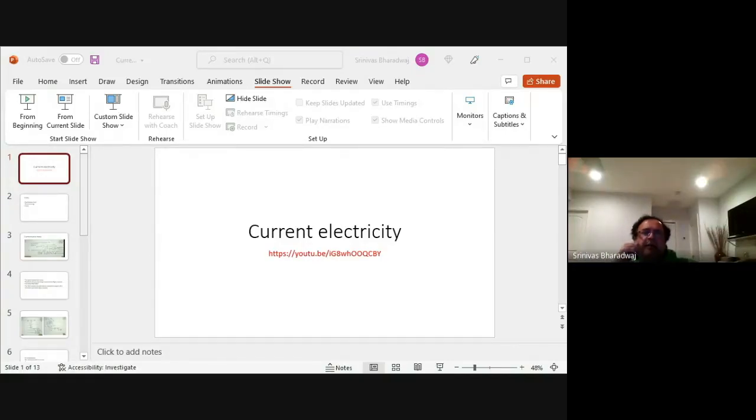Now, an ideal battery will have no internal resistance, but most normal batteries will have an internal resistance, which will get added to the RL, the load resistance. The voltage that is listed on a battery is its open circuit voltage. So if you add a load resistance, you have to also add the internal resistance. So when you do V equals IR, you have RL, the load resistance, plus the internal resistance to be added when you calculate the current. Okay, so that's how these things are done.